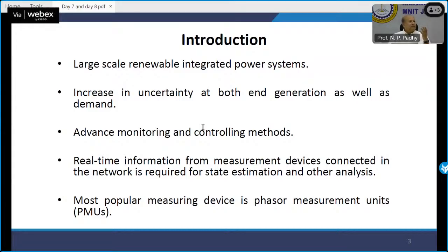So how do I determine them? We know how to determine the losses of a steady state system or a frozen system or a pseudo system. But for a real system, no one can measure the losses. Now there are data-driven techniques which have evolved, which can easily measure the losses of the distribution system. We'll be happy to know even the topology estimation works. Even if a line comes out of the system, the voltage can be estimated. So you need not work out load flow analysis again and again.